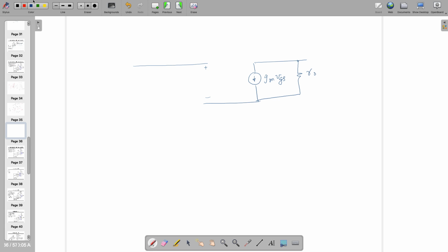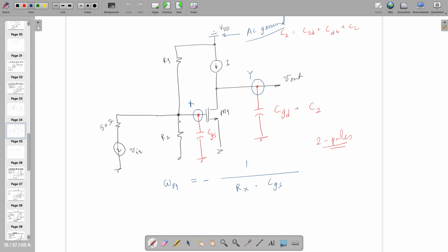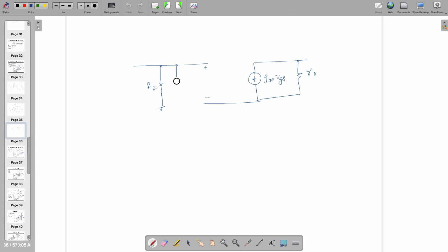So at the input side, there are two resistances, R1 and R2. So this is R2, which is already here, but R1 will also go to ground. This is VDD, but this is AC ground right now. What we are doing is AC analysis, so all DC goes to zero. And here there is a 50 ohm and there is Vin, but Vin will be shorted because we're following the Thevenin. And I'm interested in finding out